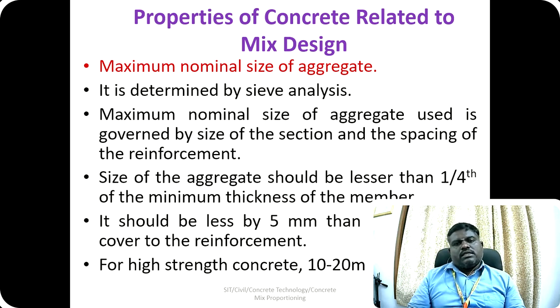The size of the aggregate plays an important role, and the size of the aggregates is determined by using sieve analysis. The maximum nominal size of the aggregate used is governed by the size of the section and the spacing of the reinforcement. The spacing of the reinforcement is a primary thing. Based on that, we can choose the size of the aggregate.